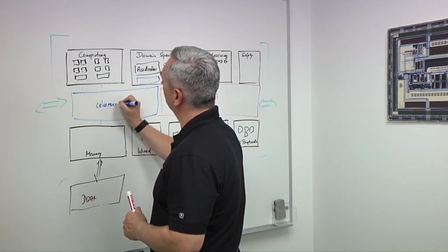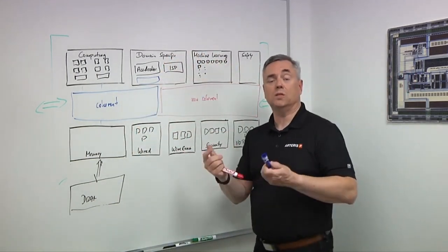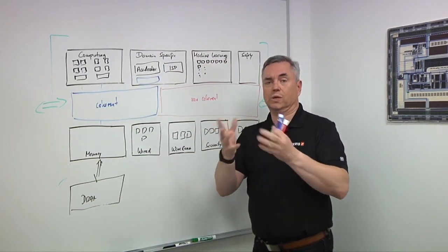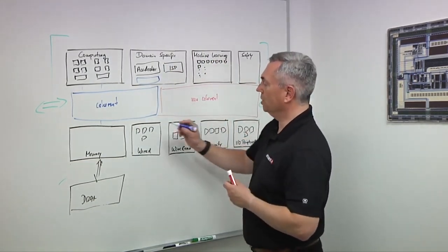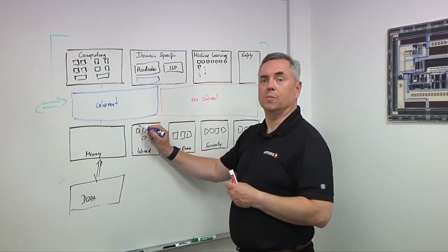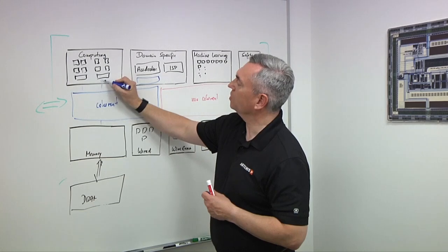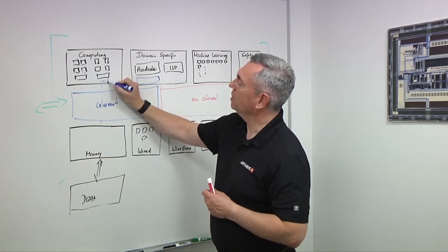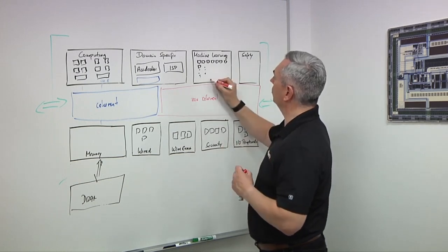So now that's a high-level picture. Who actually needs to talk at which level? Who needs to talk coherent or non-coherent to each other? And then one thing you pointed to with your questions already is these guys, when you license them, they may have all different interfaces. So here you may have something like a CHI.E interface or CHI.B. Here you may have a bunch of AXI.